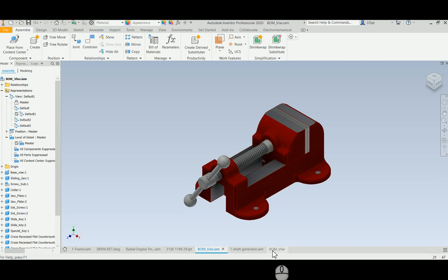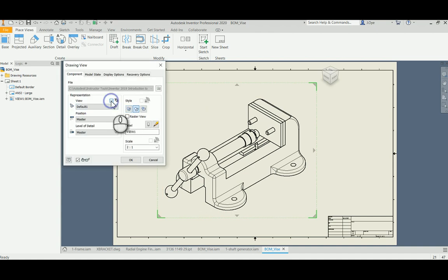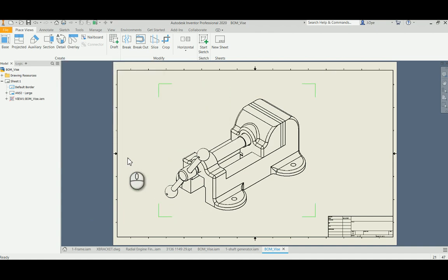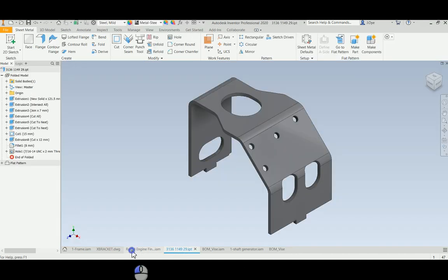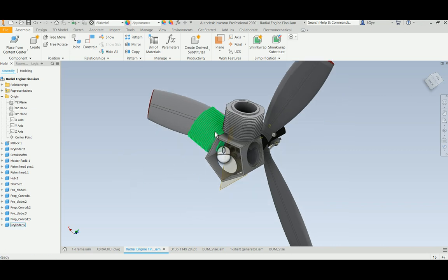All right, next thing in relation to mirroring parts within your assembly file. So I have these cylinder heads here, and I want to add another one over to the right here. So if I go into my pattern and then mirror, Inventor has kind of updated this dialog box. These work planes, these three work planes, YZ, XZ and XY, used to be placed horizontally within this dialog box, and now they just changed it to vertically.